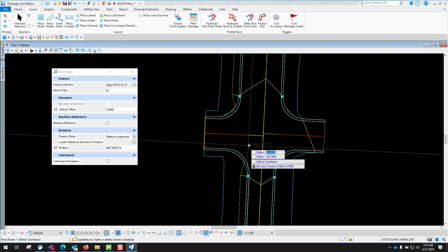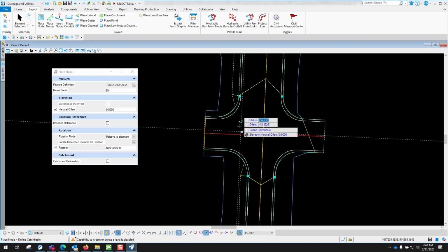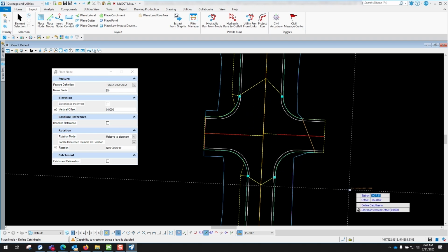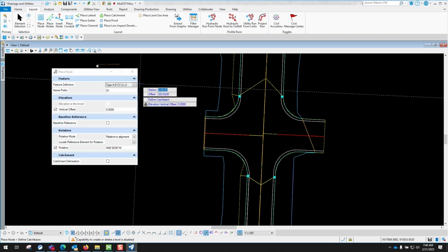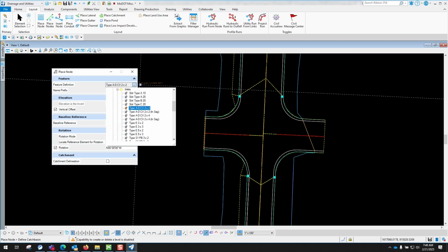And then I have a couple manholes right in here, which all this water is going to hit, and then flow out to a certain spot right over here. So let me go ahead and change my feature definition, change my groups here to the manholes, and the manhole that I'm going to use for our example is going to be the precast 4 dash flat.